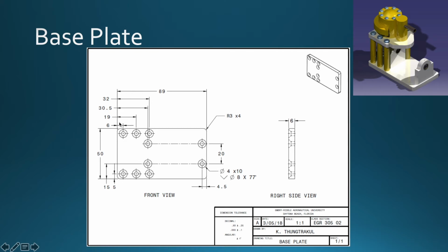So now we have the base plate. This is what the entire engine sits upon. These countersunk holes, their outside diameter and angle, had to be estimated based on the provided drawings because they were not specified, so we had to use our best judgment to make this plate. There are 6 holes for the pillars and then 2 for each of the bearing plates, which support the shaft.